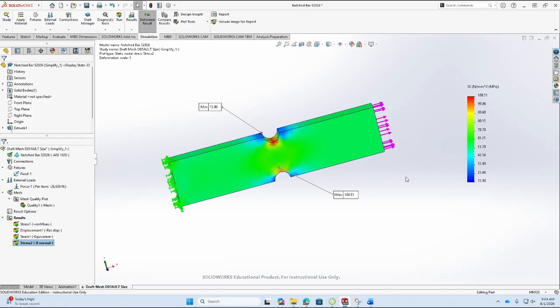So the stress that we calculate as gross stress, right, which is away from any of the concentration points, we reasonably expect that that number should be correct in our hand calculation, because there is no big change happening, the loads are applying in a normal manner. So that's why I will use that number.